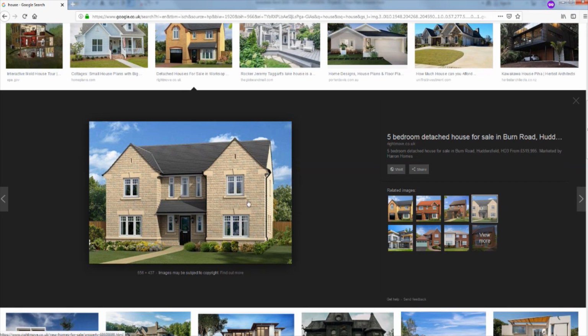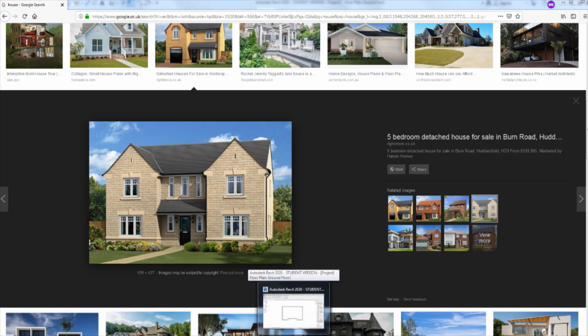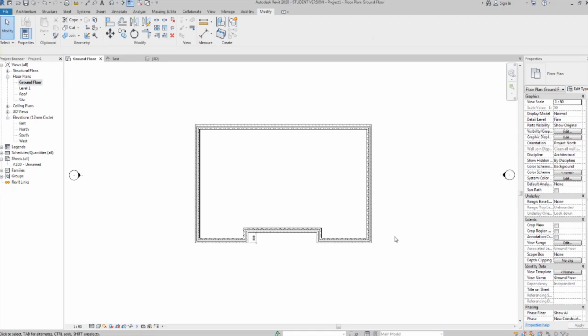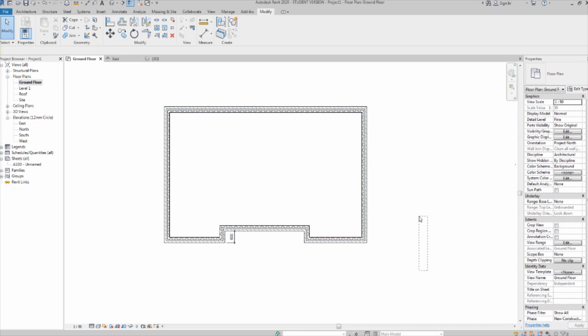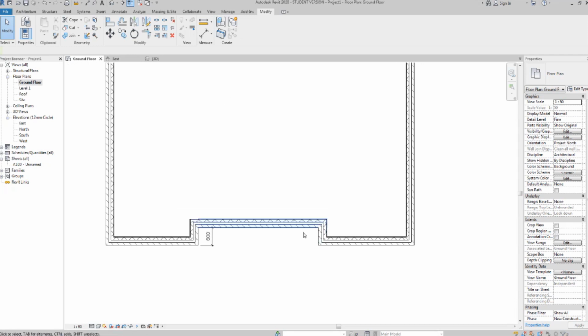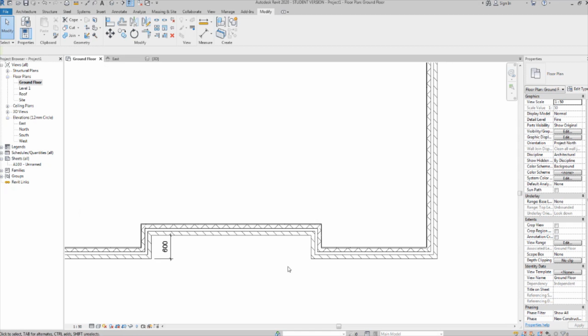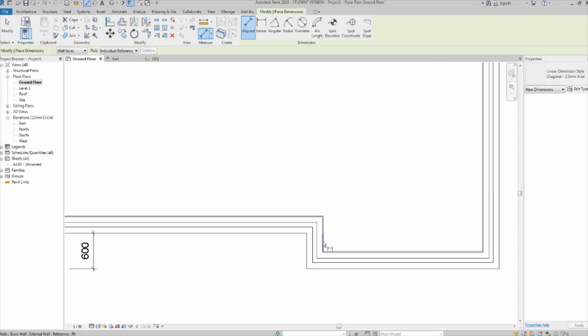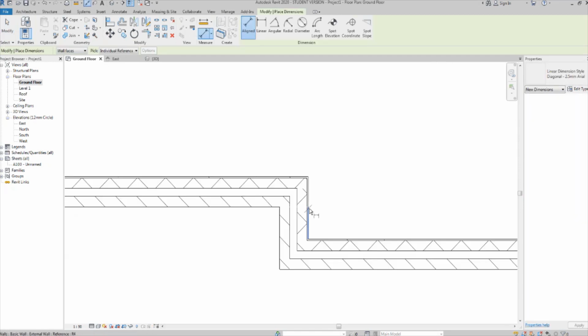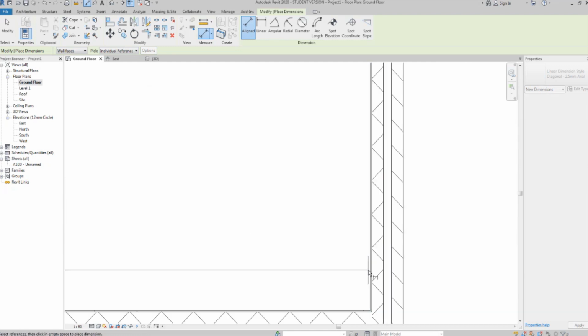Now, I want to create the exact same walls on the upper floor. Without these pictures here, we'll worry about these later in another video maybe. Okay, so if you go back into your Revit and select, before we do that, let's just sort out these wall positions here. So exactly the same thing, hit the DI key to get the dimension tool and dimension this.